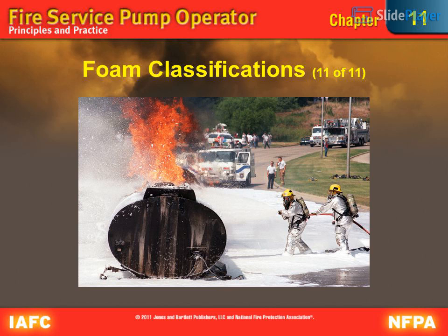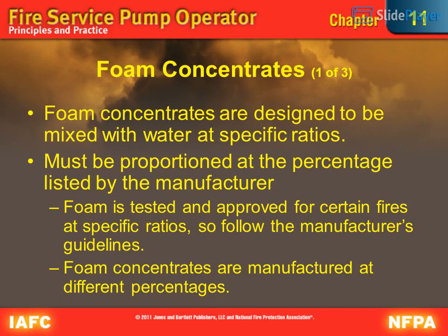Foam classifications, 11 of 11. Foam concentrates, 1 of 3. Foam concentrates are designed to be mixed with water at specific ratios. Must be proportioned at the percentage listed by the manufacturer. Foam is tested and approved for certain fires at specific ratios, so follow the manufacturer's guidelines. Foam concentrates are manufactured at different percentages.